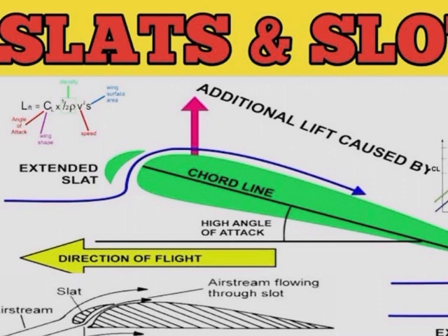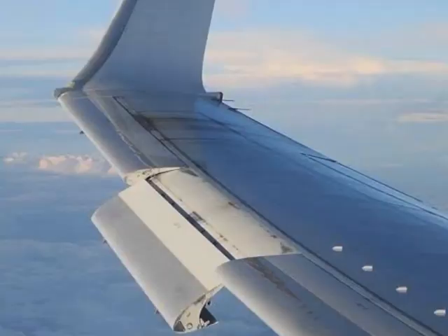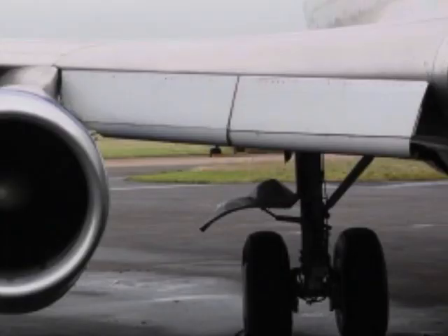So the problem of the curvature will be solved, mainly in the leading edge of the wing, but still we have the problem in the trailing edge of the wing when we extend the trailing edge flaps; we will look at it later. The leading edge flaps have only two positions, which are extend and retract. And besides, we do not have any anti-ice system available for the leading edge flaps, because they are attached in the area where the wing is thick.